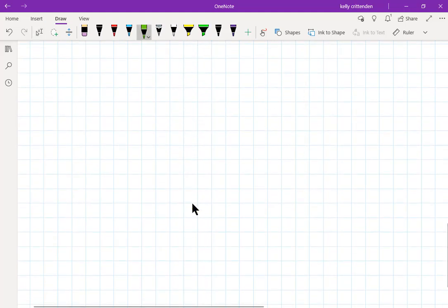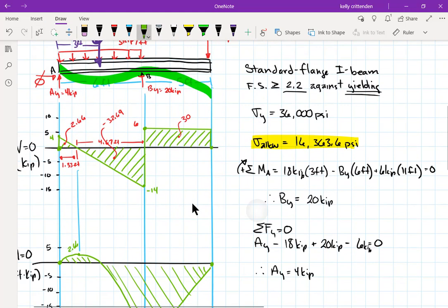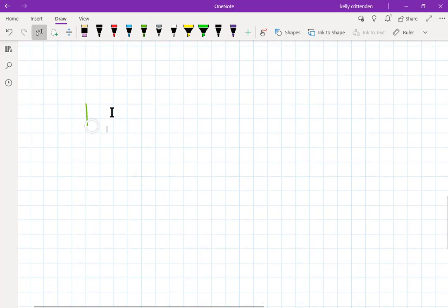So the shear at that section was this little triangle. So this was what the shear looked like in that section. It started at 4 and it went to 0 kips. So that was the shear force in that section. So remember, the slope of the moment diagram is based on the shear plot. I guess the magnitude of the shear, not the slope of the shear, is the slope of the moment diagram at any point.